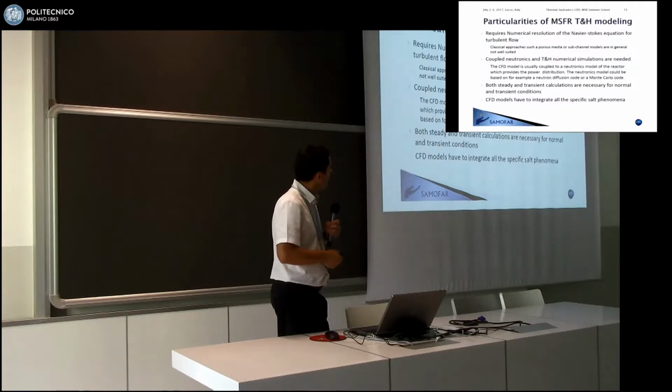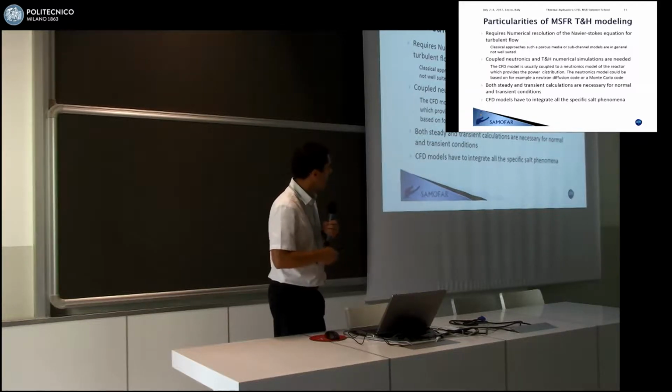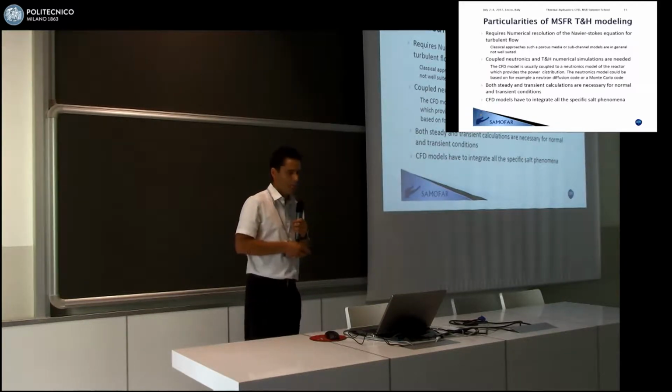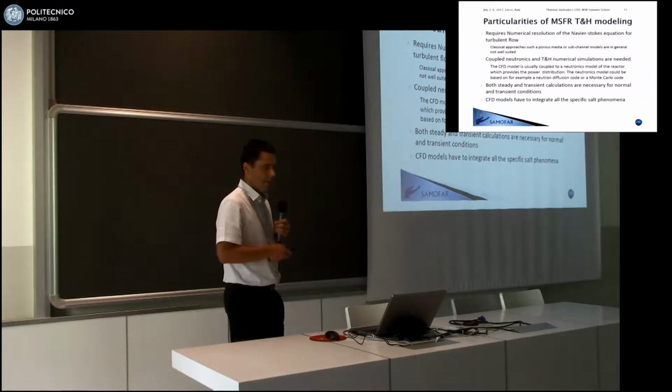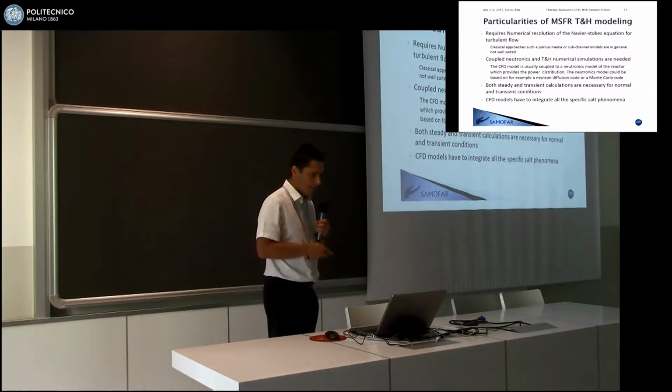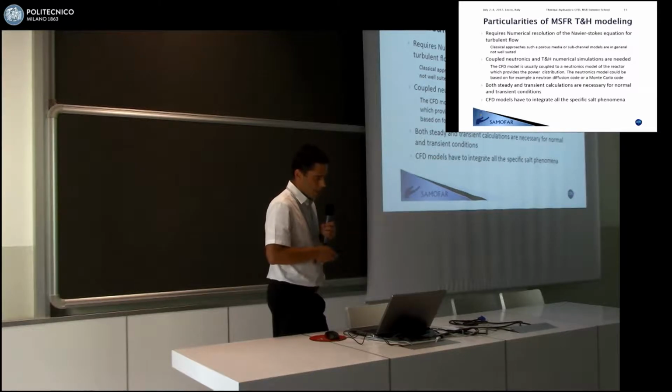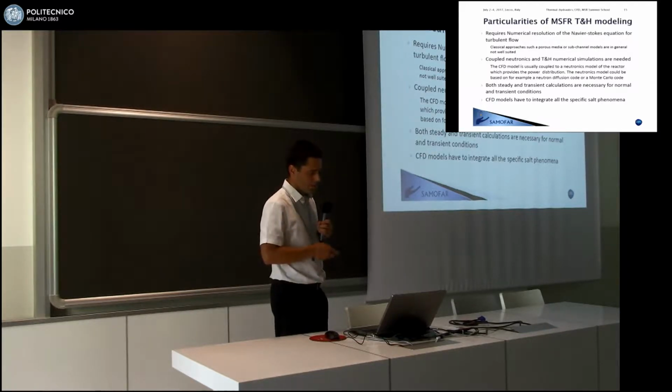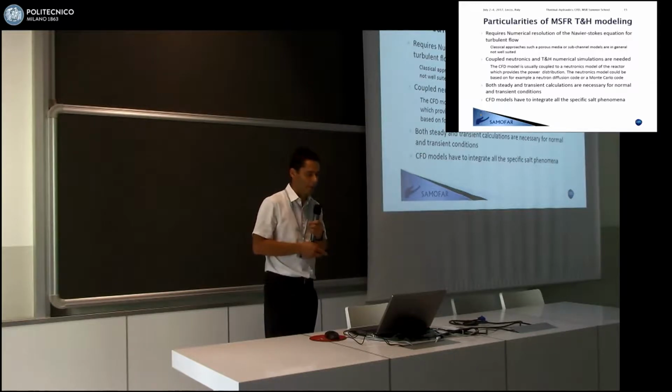All right. So what are the particularities of a molten salt reactor for thermohydraulic modeling? Well, you will have to solve the Navier-Stokes equations. This is not an easy task from a numerical point of view. You will have to run coupled neutronics and thermohydraulic simulations. It won't be a good approximation if you try to do separate calculations like you do in PWR.